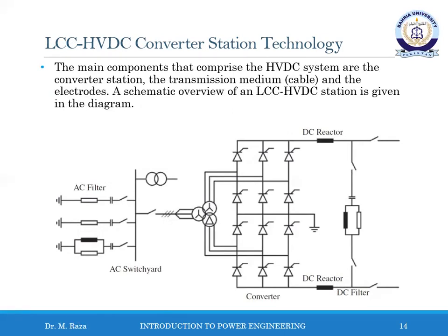Since the DC voltage is higher than the maximum blocking voltage of a single thyristor, several thyristors are placed in series. Similarly, the current capability of a single thyristor can be increased with the connection of several thyristors in parallel, which, however, is normally not needed. Normally, the thyristors are installed in modules which are placed in a stack, making maintenance straightforward. The thyristors can be triggered electrically or by using light.